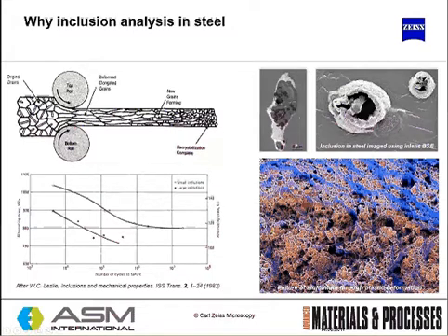So, for example, this is a typical mixed inclusion, likely to be a sulfide and oxide inclusion, slightly elongated. You can also image this very beautifully with an in-lens backscattered electron detector, and this is the result of such an inclusion, which is a fracture. This is a fracture surface in an aluminium sample, and the likelihood is that this crack has propagated from an inclusion or a piece of porosity.